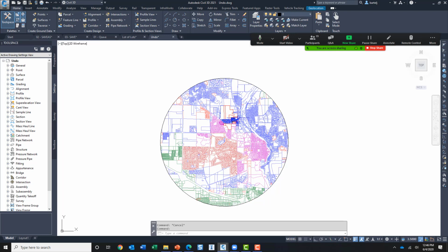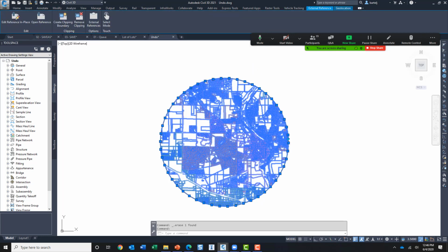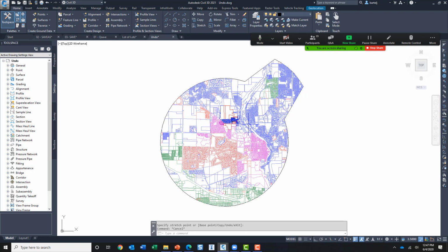But if you're X-referencing files, we would take and clip that. I'm going to take my polyline out of here, and then if we were to make adjustments to this, going back to some of the grips stuff that Jeff showed us the other day, assuming those values were on, I would have only loaded the information that shows up in the window. If I were to change the outer boundary, Civil 3D or an AutoCAD based application would automatically reach back in and demand load just the geometry that we need because we've got it indexed.